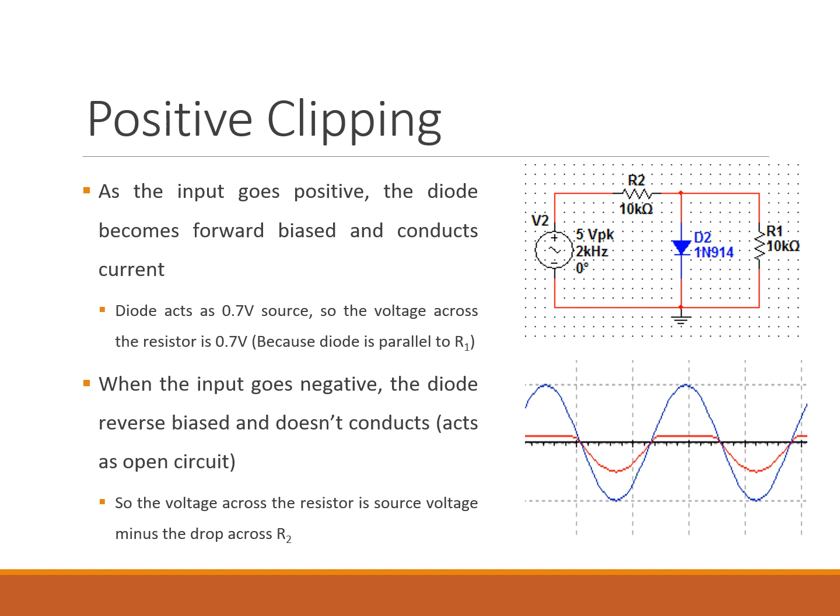So here's what's going on. Take a diode like the 1N914, right? It's wired in parallel with a resistor across the output. During the positive half of the input waveform, the diode becomes forward biased. It starts to conduct. This limits the voltage across the resistor to approximately 0.7 volts, which is the diode's threshold. Any voltage above 0.7 volts just gets clipped off and the output voltage flattens at that level.